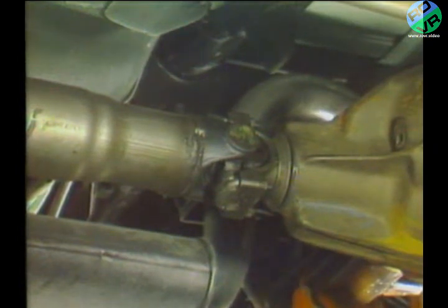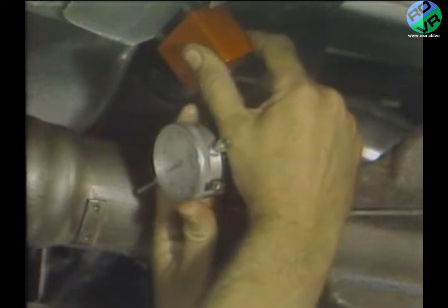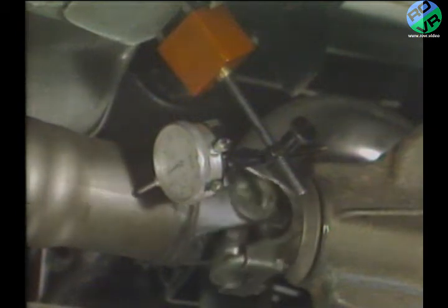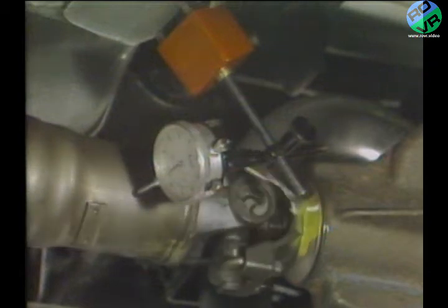A driveline runout check will also tell you about the condition of other related components, like the U-joints, companion flange, and drive shaft. When isolating the problem to driveline alignment, check the drive shaft runout at each end and at the center of the shaft. Maximum allowable drive shaft runout is 35 thousandths of an inch.